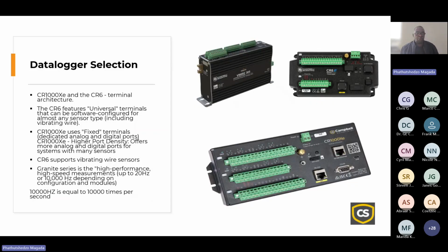So we have different data loggers displayed here. We have the Granite series, we have CR6, we have CR1000XE. So you need to assess your situation and choose the data logger that is applicable in your site. For example, the main difference between CR1000XE and CR6 is the terminal architecture.